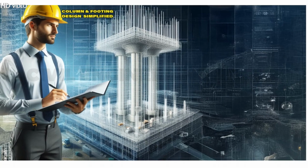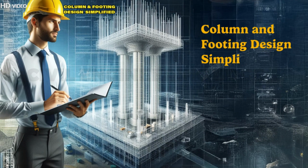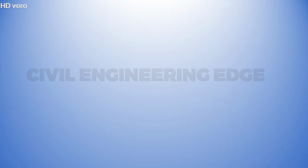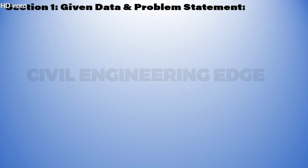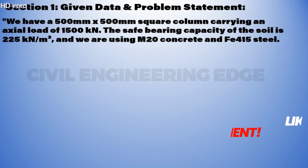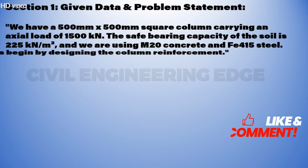Section 2, column design. Load on the column W equals 1,500 kilonewton. 1. Calculate the factored load. Pu equals 1.50 into 1,500 is equal to 2,250 kilonewton. 2. Calculate gross area of column. A equals 500 into 500 is equal to 250,000 square millimeter.